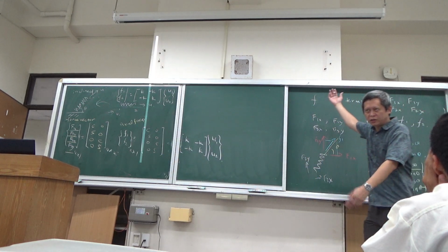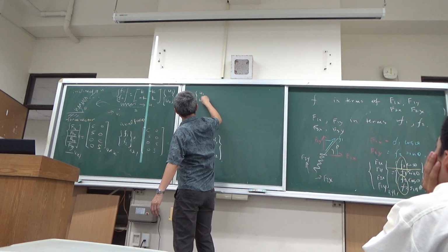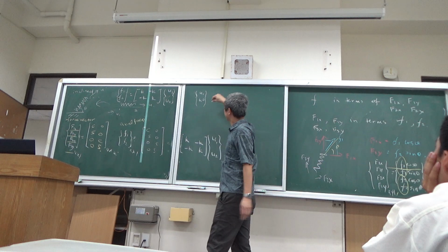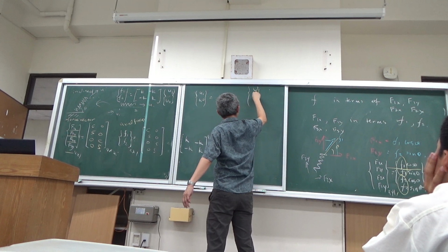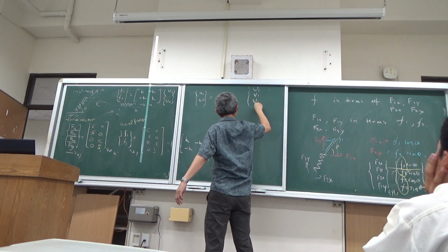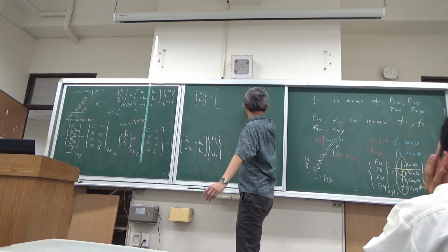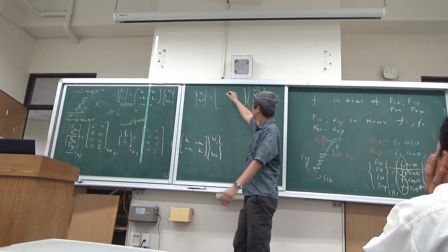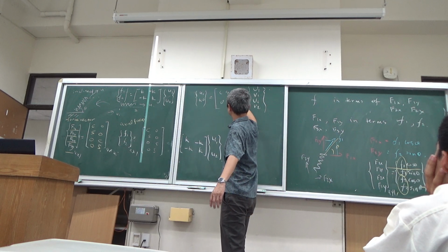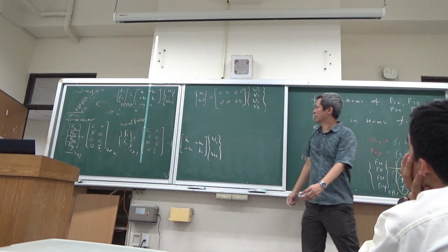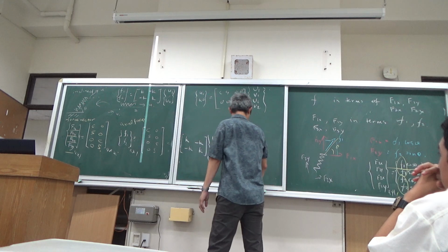And can you recall what we wrote for U1, U2? You can rewrite this in terms of the global displacement, big U1, big V1, big U2, big V2. In terms of the projection, do you remember? Just now we wrote this as C, S, 0, 0, 0, 0, C, S. Okay? So this expression can be further written as